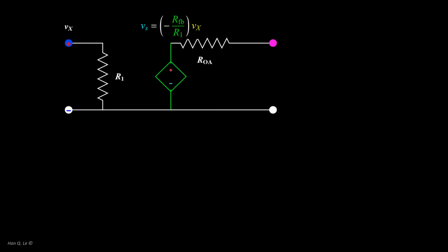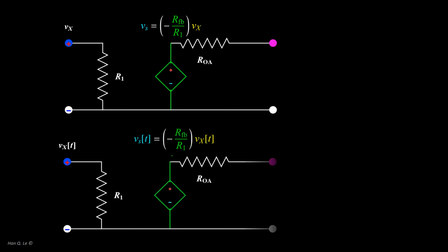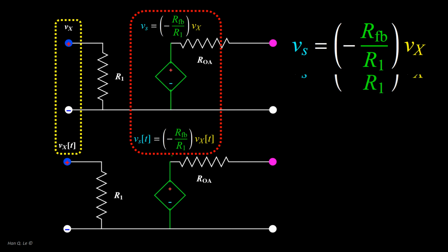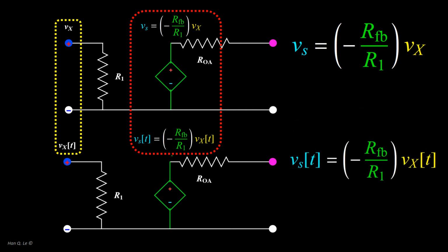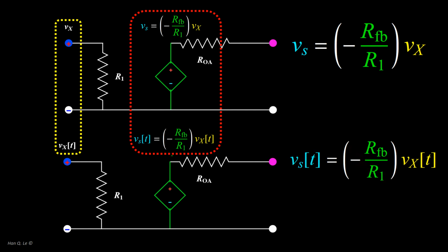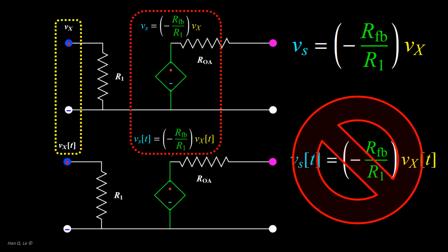Along the same line of discussion, an issue is whether the simple linear amplifier model, which is derived for steady-state condition, is applicable to time-dependent voltages. The discussion of Part 1, Step 1.3, states that it is incorrect to extrapolate a steady-state causal relationship, as shown here, to time-dependent voltages. In other words, the simple linear equation is correct for constant input voltage Vx, but cannot be correct with AC voltage Vx.